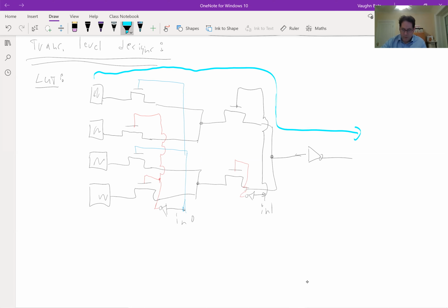And I got a potentially big routing wire after this. So I put an inverter here so that I can basically increase my drive strength. Now any downstream capacitance gets discharged to ground or VDD by this inverter, rather than having to drain all the way back through these pass gates. Okay, so that's my 2-to-1 mux.